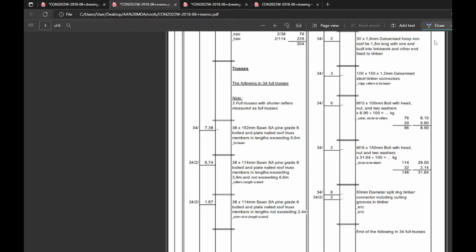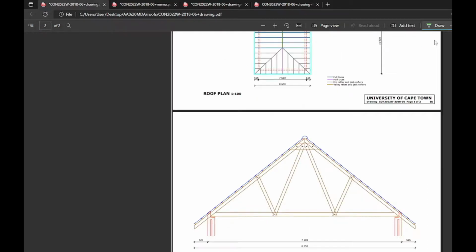Roof ties. Timber steel connectors. Not exactly obvious every time. Let's see how this one comes out. So it's 3, 1, 2, 3. Okay, so you can see clearly that in the absence of any connectors, we have to assume they are fixed somehow. And in the diagram, if there's a dot, dot would be bolt. No dot is, we'll call it nail plate. In the absence of any visual indication, we have to assume that there's a nail plate there. Something has to be holding those pieces together, and it's a nail plate.